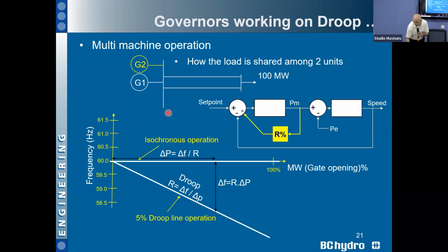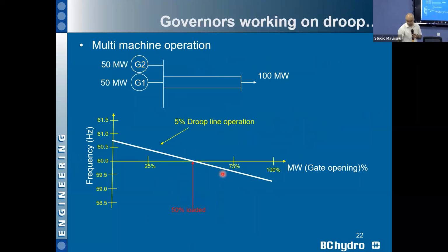In this case, the droop means the slope of this line, which is the feedback factor. If you have a bigger feedback number, the droop will be bigger, because this delta P will be multiplied by R and given as frequency, right? So therefore delta P multiplied by R is given as frequency change. So this is how the equations work. I know you all know about that one.